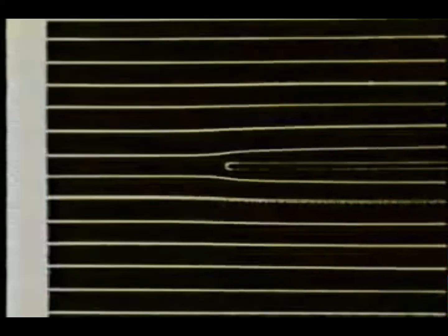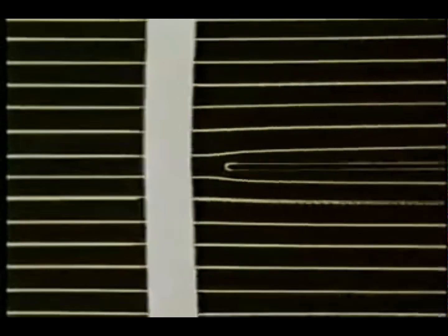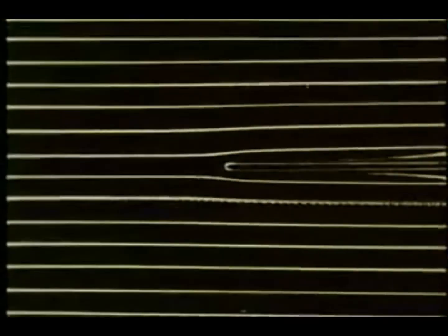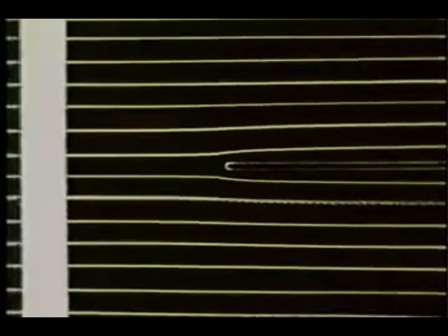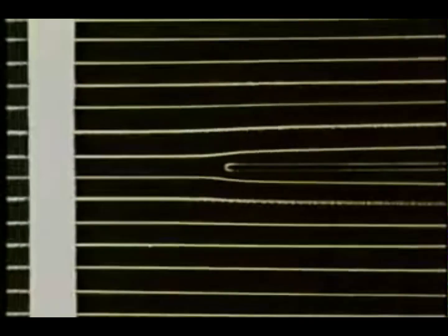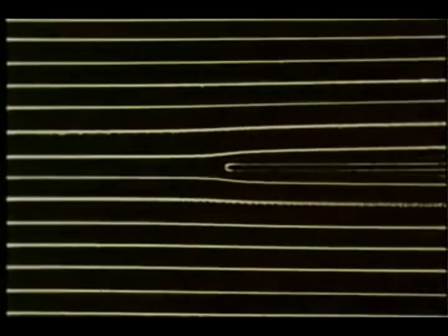Here is the flow over a plate. The flow is two-dimensional and laminar. Upstream of the plate, the flow is still uniform, but in the fluid layers near the plate, the velocities are much lower and vorticity is present. In the narrow boundary layer region adjacent to the plate, the shearing forces and inertia forces are of equal importance in determining the motion of fluid elements. Outside of this region, the shear stress can be neglected.